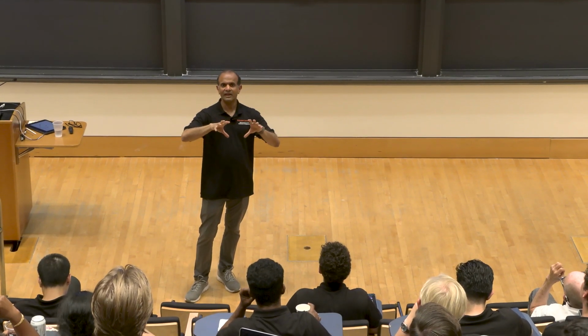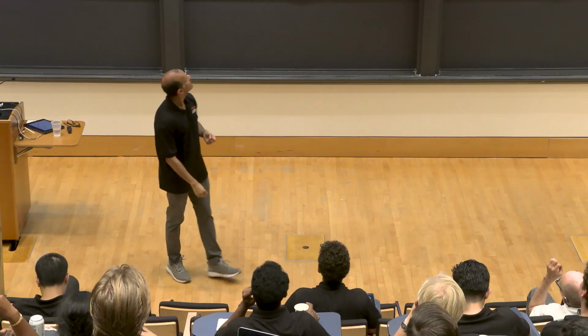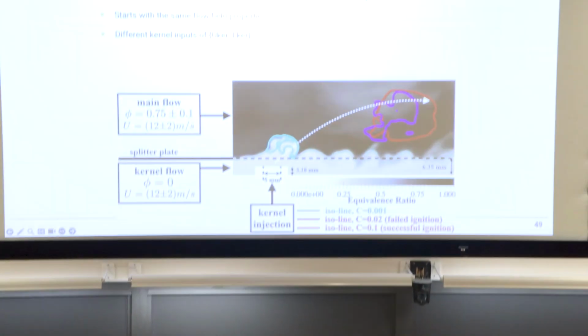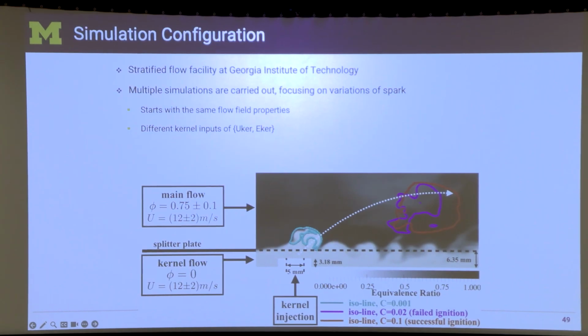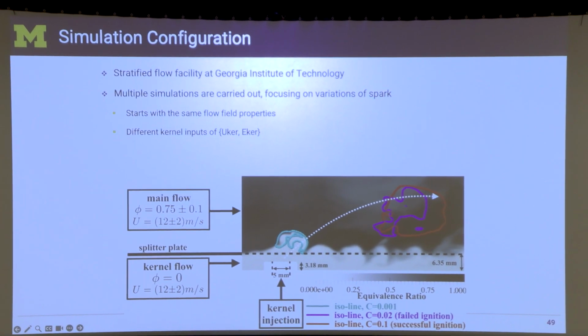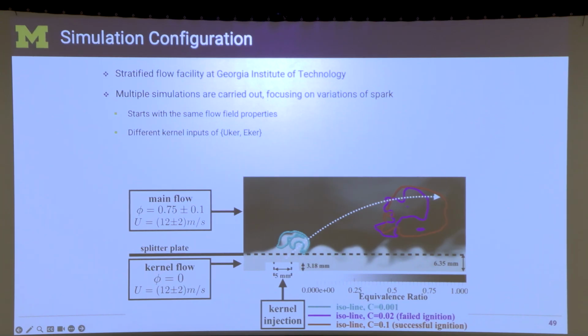It ionizes the air, heats it up a lot, and then ejects this plume into the flow. The flow itself contains fuel and air coming to their mix, and they're coming in, not fully mixed, but somewhat mixed. They're coming in from the left like a jet in cross flow. This plume comes over, and it's supposed to interact with this mixture and then ignite it.